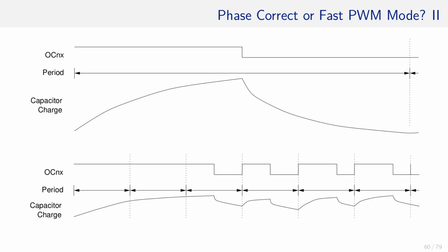Imagine a very long period with 50% duty cycle. In the on time, you need to charge a capacitor which is able to carry over and supply voltage while the pin is turned off. In long periods, the capacitor has to be charged a lot, hence a large capacitor is required. A shorter PWM period results in a smaller capacity requirement for the capacitor, since the charge and discharge times are much shorter now. This allows physically small-sized external components and therefore reduces total system costs.